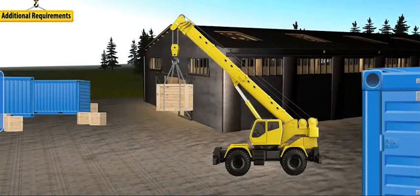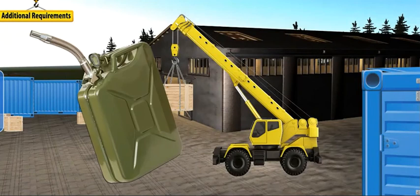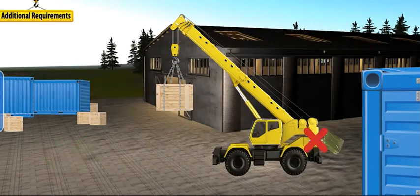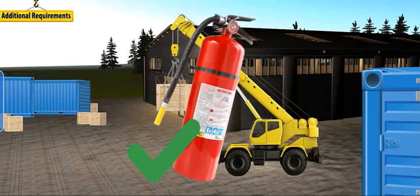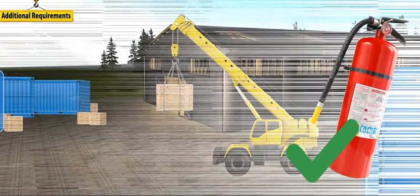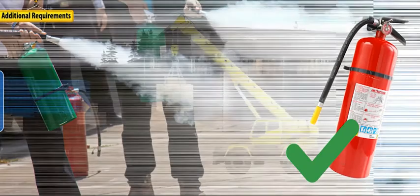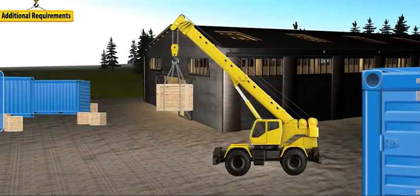Keep the operator's cab clean and orderly, and make sure all equipment and accessories are properly stored. If you need to use portable containers to refuel cranes, only use approved safety cans with automatic closing caps and flame arresters. Never refuel portable cranes or hoist machinery components while engines are running. Finally, an approved, fully stocked fire extinguisher must be kept in or near the crane's cab at all times. Operators will need to be trained on firefighting procedures, including how to use the fire extinguishers present near their crane.